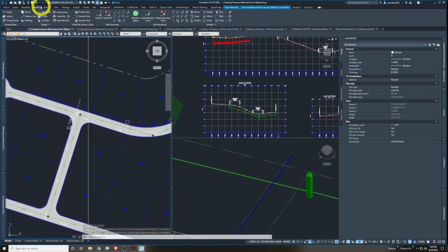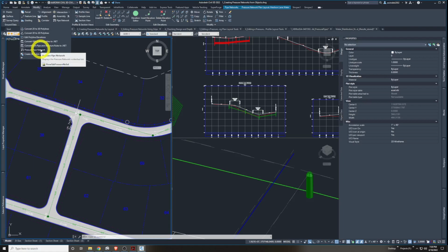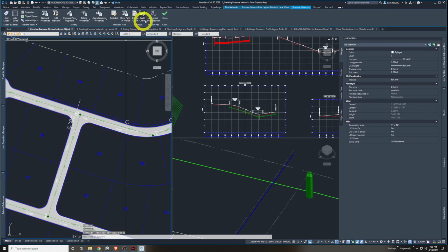Furthermore, you could go to Modify. This takes you to gravity pipes, my mistake. But if you go down here further in design, you have all your Civil 3D objects we've been learning about, minus grading and intersection at this time. And we'll go down here to Modify Pressure Pipe Network to get our pressure network's main header contextual ribbon up.